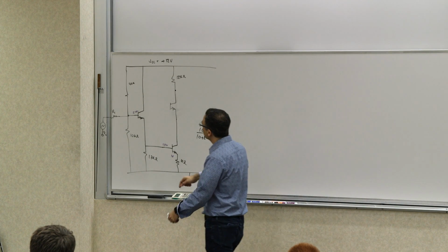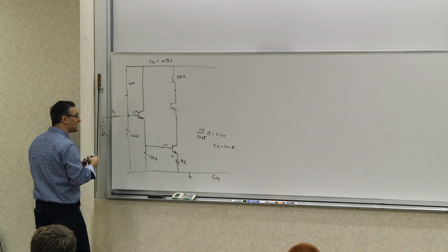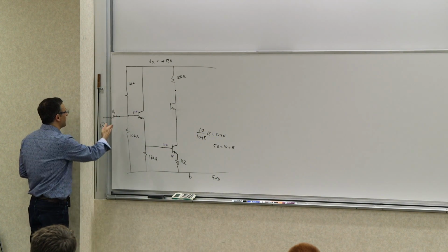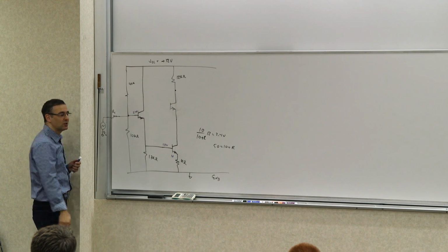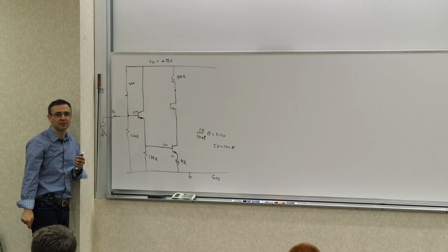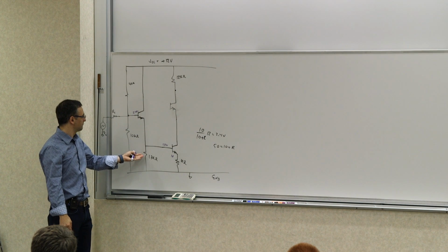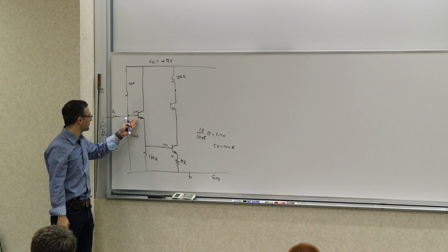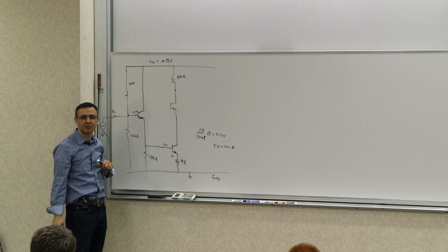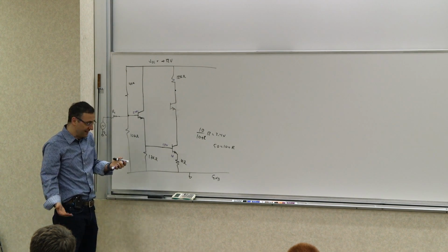Right, because this is an AC source, right? From a DC perspective, this is a short. So this is shorting it DC-wise to ground. So all of this goes to nowhere, basically. This is going to turn off, nothing's going to turn on. So what do we do in a discrete design?